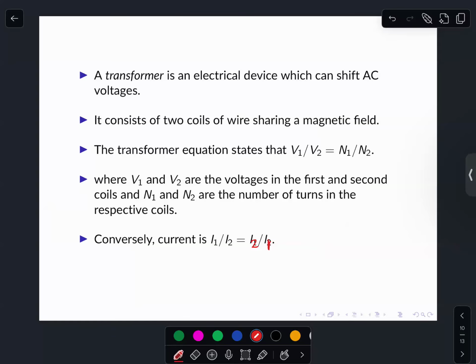Or, say you've got 12,000 volts that you want to become 120 volts. This is actually practical. This is what your electrical power grid does. The transformers outside your house do this. The power lines have more than 120 volts on them. I don't know the exact number, but say it's 12,000. There is inside those transformers, say, 1 turn and 100 turns. 100 turns on the high voltage side, 1 turn on the low voltage side. You get 12,000 volts turned into 120 volts. You can't get something for nothing.